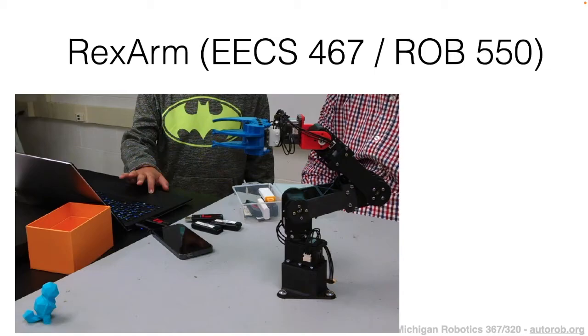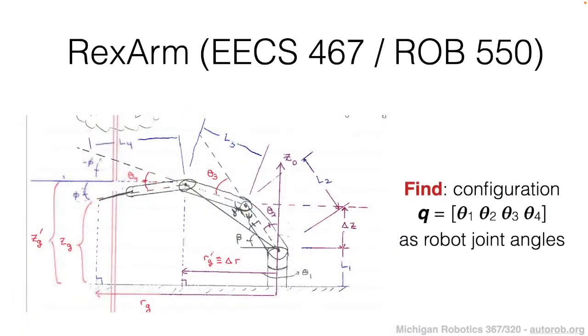and really the approach that's taken by students when they take some of these other courses for defining their inverse kinematics. One thing we can do is sketch out this robot to understand the state space. Like I mentioned, this is a 4 degree of freedom robot. It has a rotational joint around its base, so it can revolve around the scene with respect to the vertical axis of the scene, and then it has 3 additional rotational joints along each of its 3 links. Together there are 4 rotational angles that would have to be solved for within an inverse kinematics routine. These angles are depicted within this graphic here.